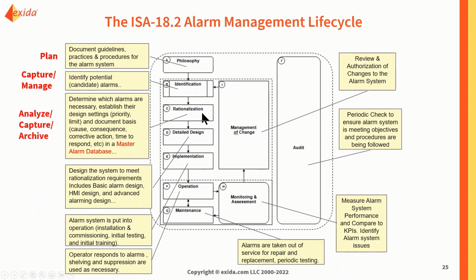And during the rationalization process, we go into a very in-depth analysis to look at the set point to try to derive the priorities based on the severity and also the operator's urgencies. And also we try to archive everything because we are trying to set up a master alarm database as well.